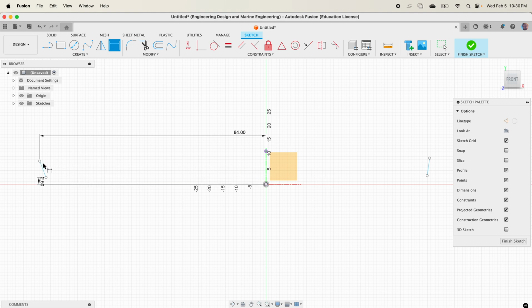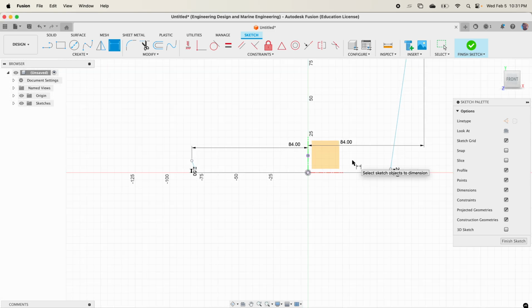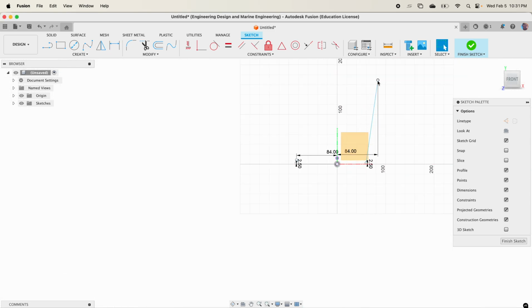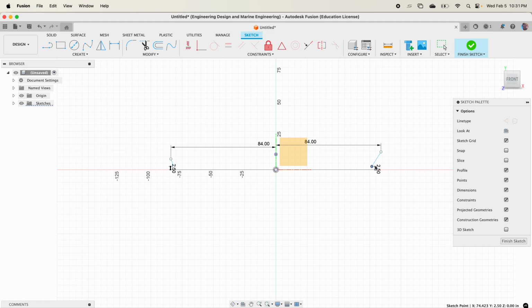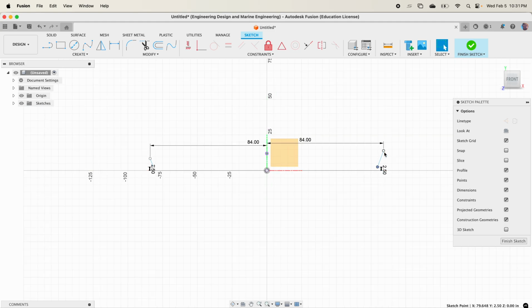And I could control for the height of the bow as well. I'm going to do the same amount of rocker on the stern, 2.5, and I'm going to do the same length for the back half of the boat and do 7 feet. Oh, and it did a thing where it went all over the place. Let's correct for that. There we go. I think that's too tall. I'm going to bring that down a little bit for the back. The back generally should be a little bit lower than the front.